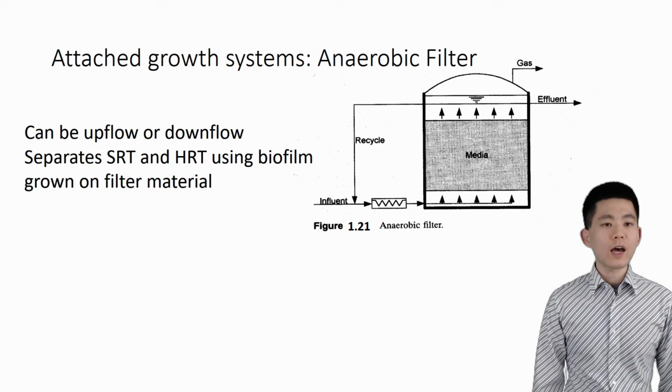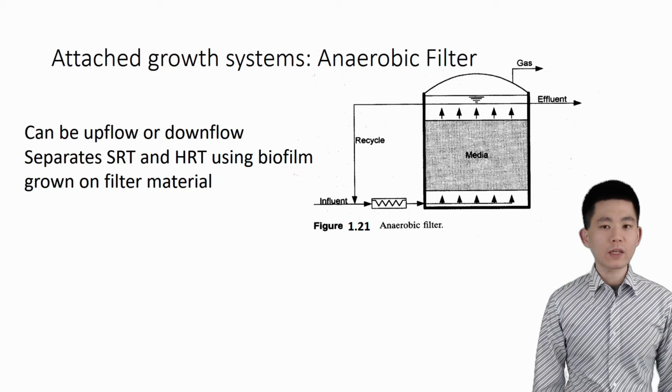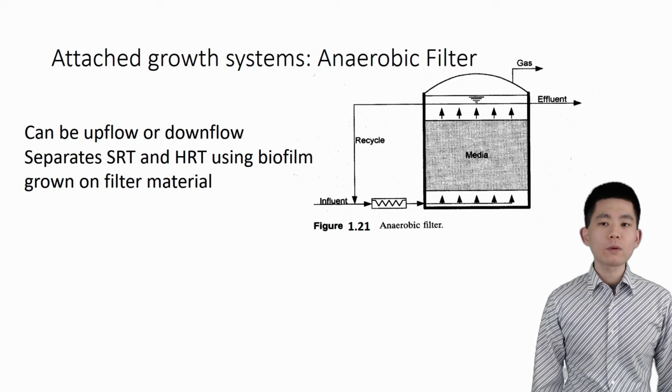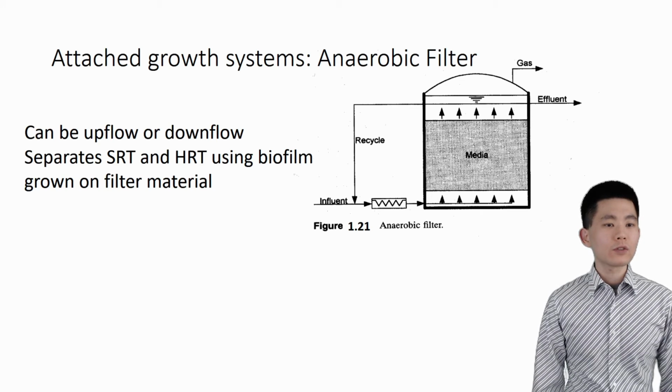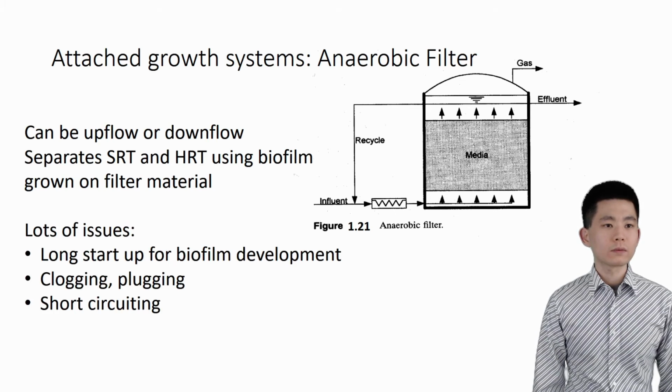In addition to the high efficiency suspended growth anaerobic digesters, attached growth digesters also have separated SRT and HRT and can be used for high rate operation. Anaerobic filter uses filter media to support the growth of biofilm.